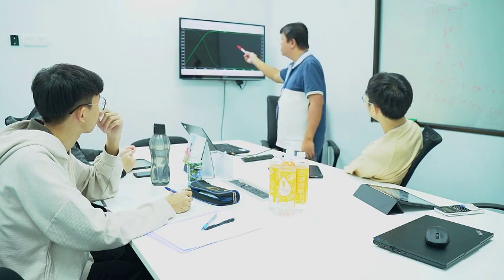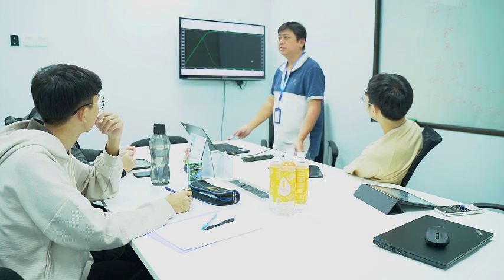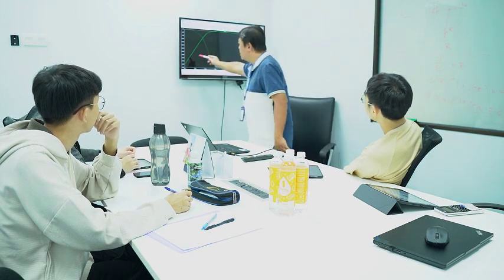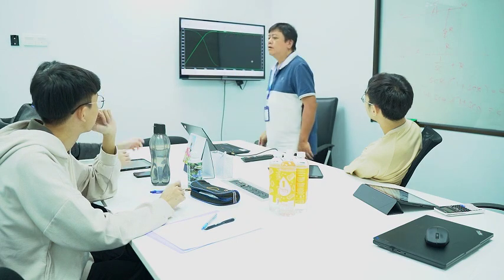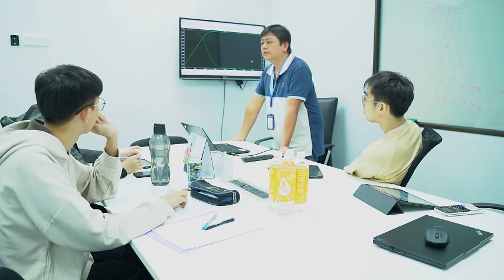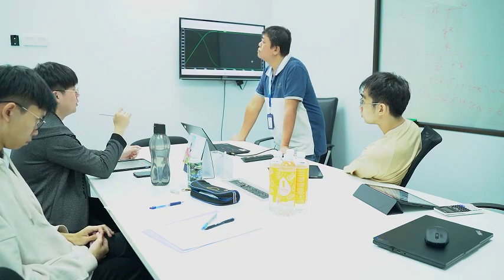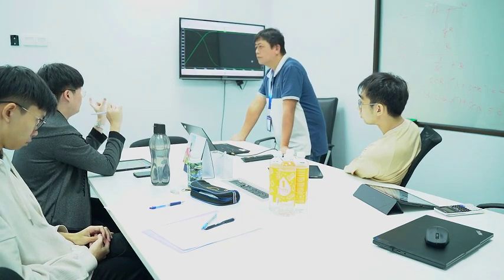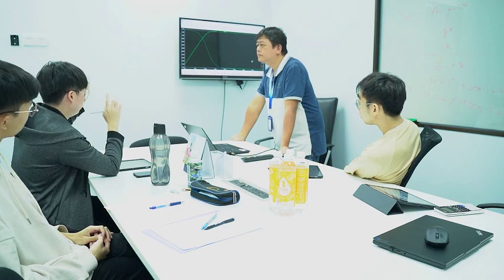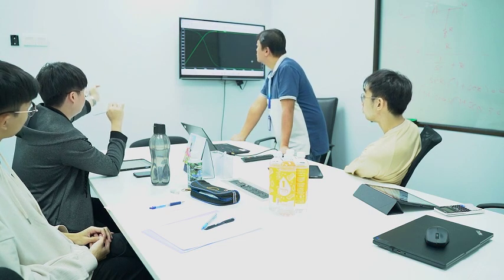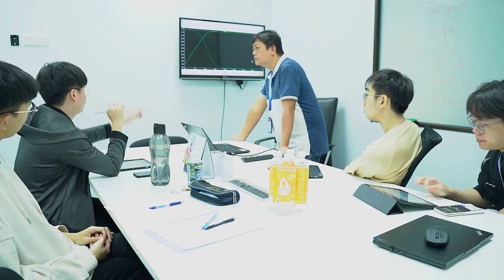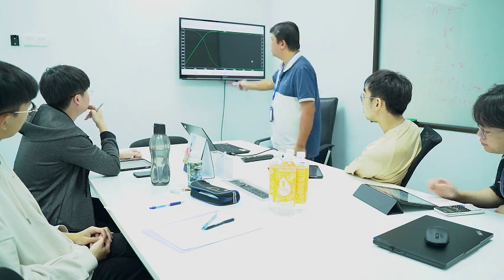Back to the question just now, I'm not sure whether it is left or right for the origin. Oh, you mean here, right? Yeah, from the origin. Because based on the definition you said earlier, for a right-hand pole it is plus 20 dB per decade, and the phase shift will also decrease when you vary the frequency towards the right side. But this one I need to check first.